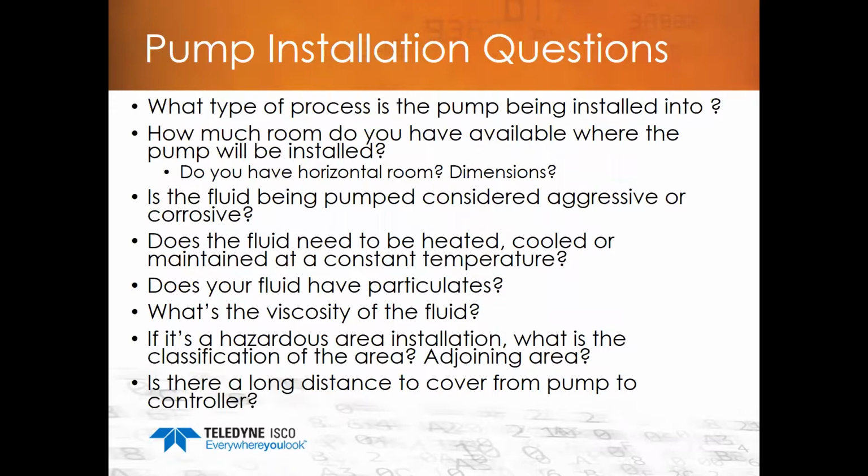Is the fluid considered aggressive or corrosive? That obviously is number one, because the pump that you're using has to be able to handle it safely and not pump it for 3 days and then start to leak, right? Because leaking of aggressive or corrosive fluid is a significant safety hazard and a danger to everybody. Does the fluid need to be heated or cooled to maintain a constant temperature? Do you need to heat it to change its properties? These are things you want to understand because it has an impact on the type and style of pump that you consider.